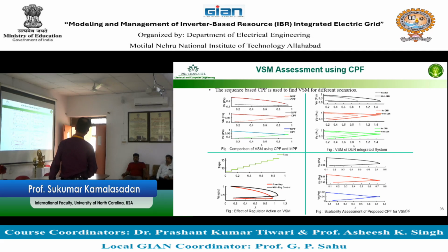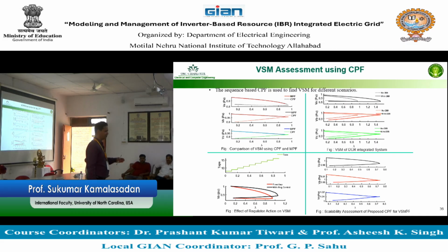What happens if there are transformer taps? Remember the LTC, OLTC on the distribution. When the transformer has a fixed tap, no tap, this is the PV curve. When it taps, the PV curve gets extended. So now you can say, I am regulating the voltage of the transformer, what will be my PV curve? I can assess that, and that is actually on the head end. You just go with the one voltage at that point and see what the PV curve is at that point. We proposed this, and there is a paper on it. I did not put the reference there, but you can read it.